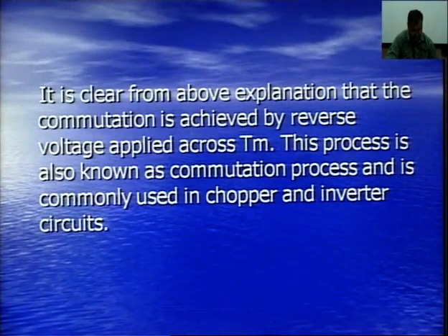In such cases, it is necessary to connect a number of thyristors in series to handle high voltages, and a number of thyristors in parallel to handle high currents. The series parallel combination of thyristors is used to handle huge electric power. Sometimes series or parallel connection of thyristors is also adopted to minimize the cost of the system. It is because an individual unit of a higher rating may be costlier as compared to a combination of multiple thyristors of a lower rating.